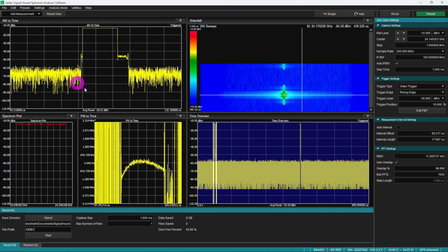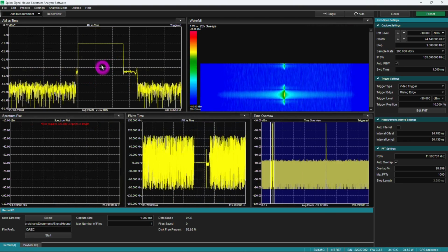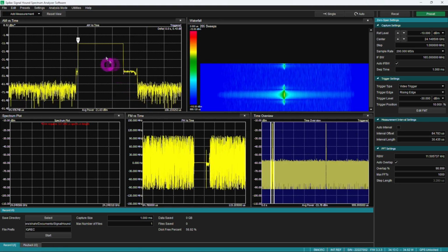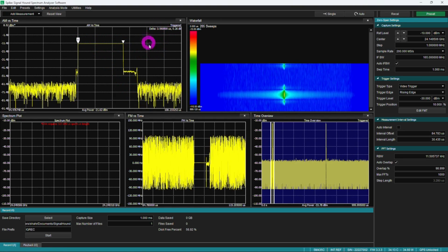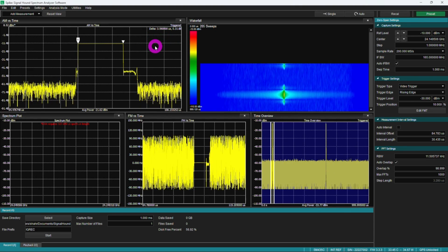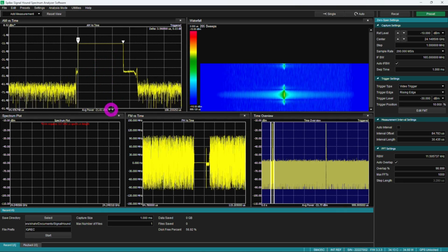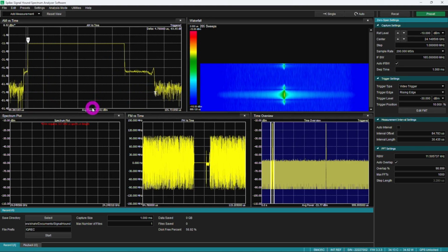Now, if you go into the amplitude versus time, we can see some interesting features of this right away. So let's place a marker on here at the very beginning of the pulse. We can also create a delta marker and move that delta marker and put the main marker here. You can see the pulse is about 3.6 microseconds, which is a little bit less than what the radar is actually telling us. But more importantly, it does have some interesting characteristics. So let's move it over here and let's zoom a bit more so we can see exactly what the pulse is doing.